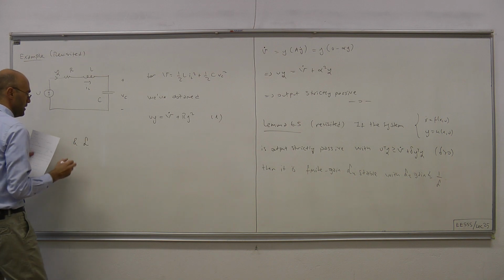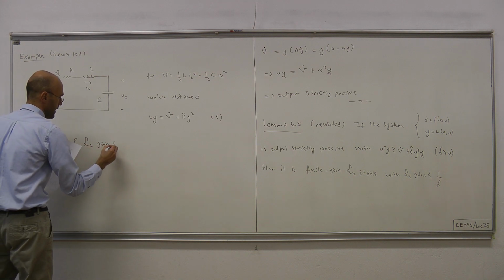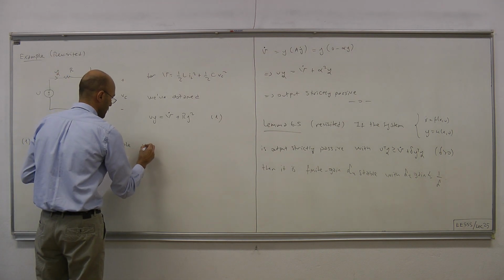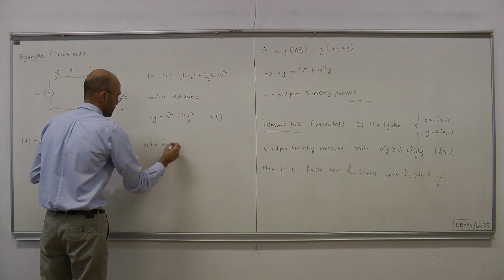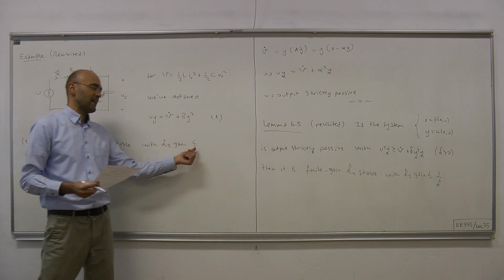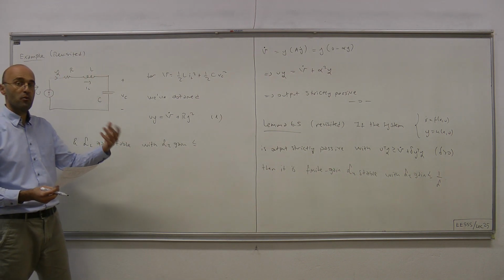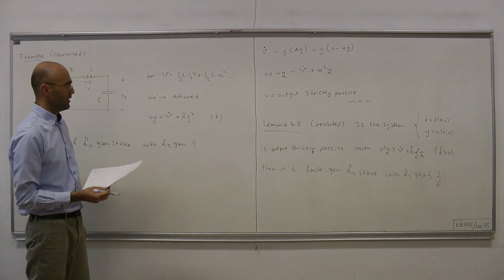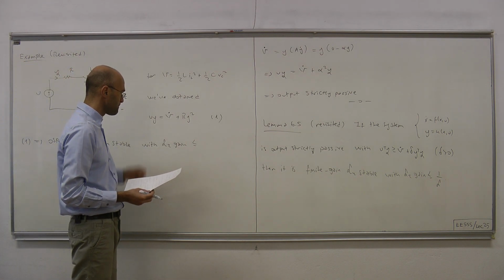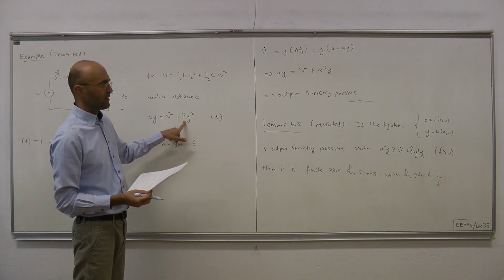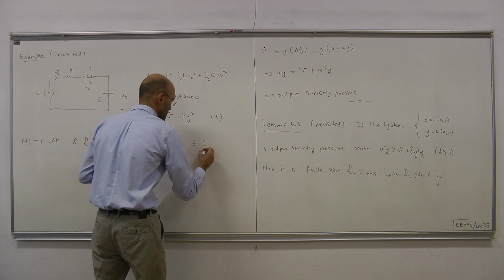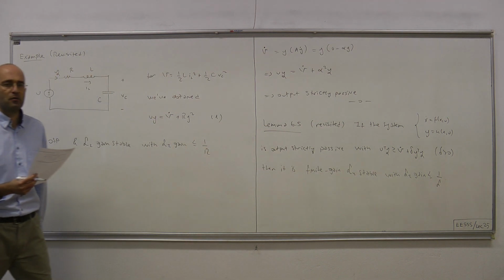So therefore that inequality implies that this system is output strictly passive. Moreover, it is L2 gain stable with L2 gain no larger than 1 over delta. In fact, in this case it exactly equals, because we can compute that using the behavior of the transfer function on the imaginary axis. Delta is R here, therefore we're talking about the conductance, less than or equal to the conductance of the resistor.